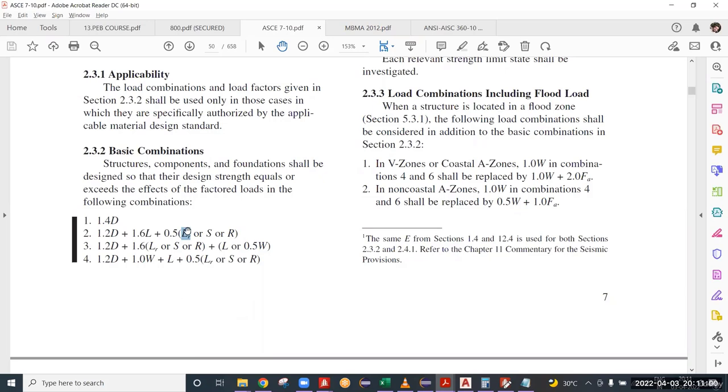So this roof live load is nothing but... actually there will not be any direct live load on the roof. What is this roof live load? It is the weight of a particular person who goes above the roof for maintenance. Like while erection, he has to clip the purlins or clip the sheeting, or he has to go above the roof, right? In that case, or while maintaining the structure every year.